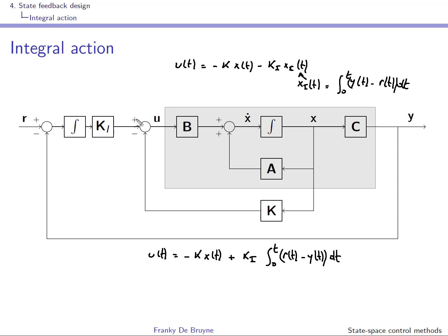Okay, so this is why you have a plus over here, and that you have the standard way of seeing things. It's set point or reference minus the signal that you're controlling, and this is producing the standard control error, which is r minus y.